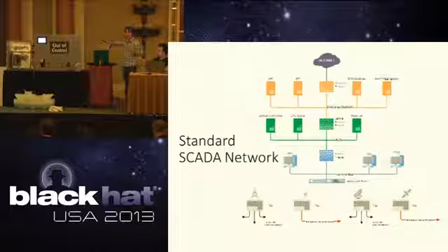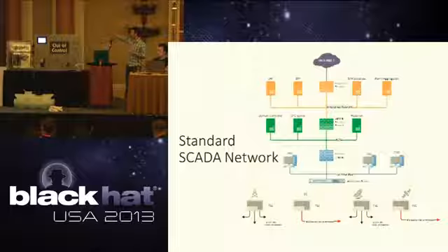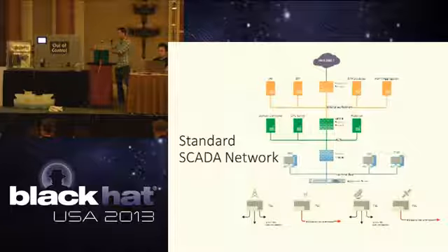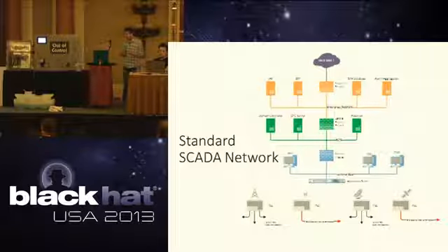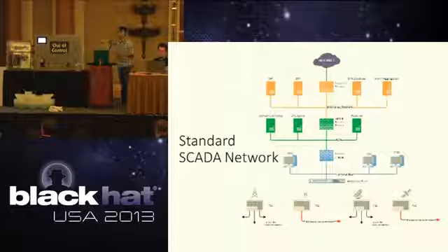And there are all different types of mediums that you use to connect that PLC up to the terminal bus, is what they call it. So that's how you get that data from the PLCs out in the field to the HMIs back at the control center. We showed some graphics here, but it can be anything from 900 megahertz radio, it can be microwave links, and it can be, of course, our favorite, a regular old cell modem that's given a public IP address.